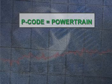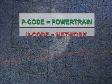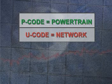Speaking of trouble codes, with the arrival of the CAN buses, you're going to see some significant differences in DTC designations. Like the P codes you are probably familiar with, other codes now use a letter prefix to indicate the area they affect. In addition to P codes for powertrain, modules now use U codes for network communication.